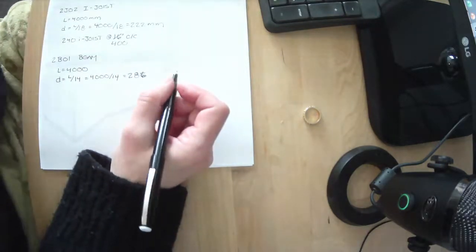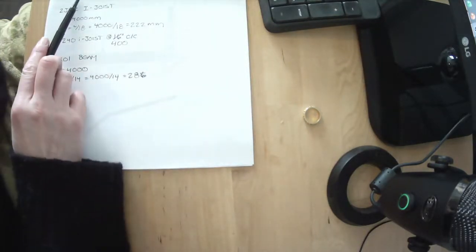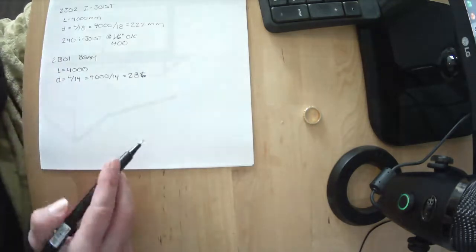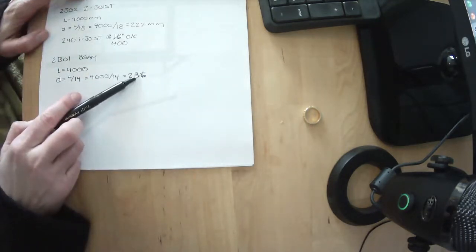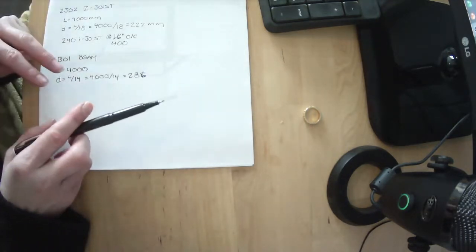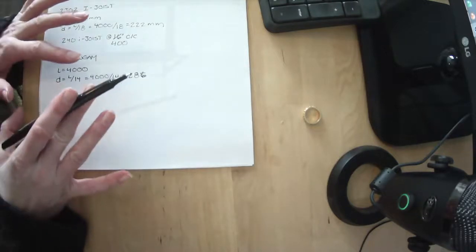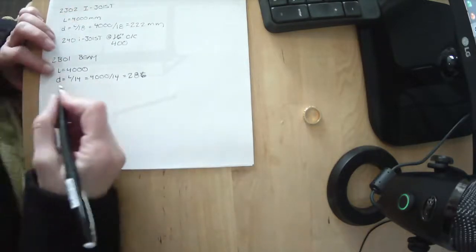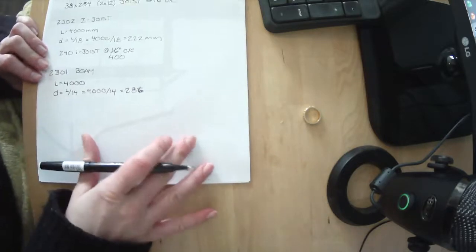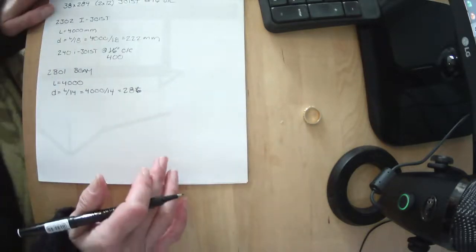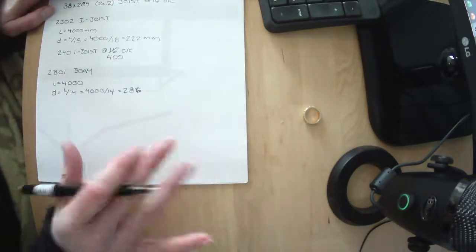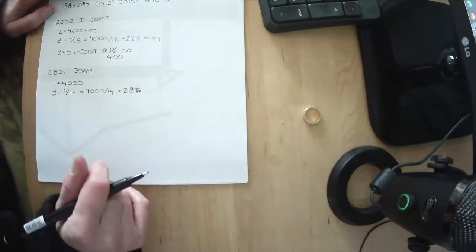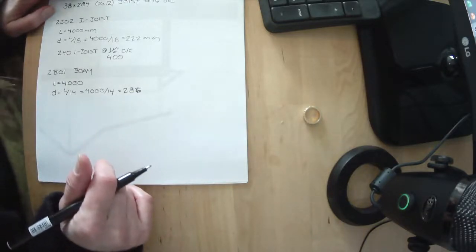It looks like our 2x12 is going to be a good choice. I know I said never go down in size, but 2 millimeters, I'm not going to freak out about 2 millimeters here. Any ones I give you in your assignment, I try to make them really obvious that you have to go up. I try not to fiddle around with that on you. I try to make it super duper obvious.